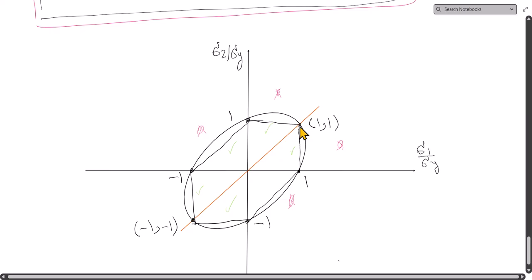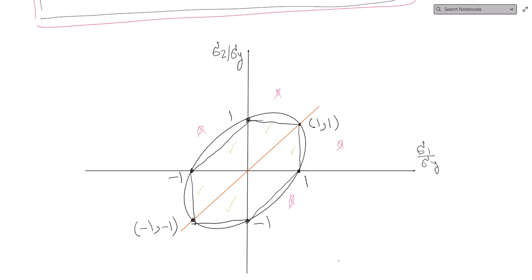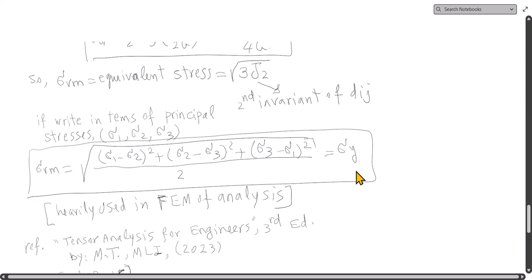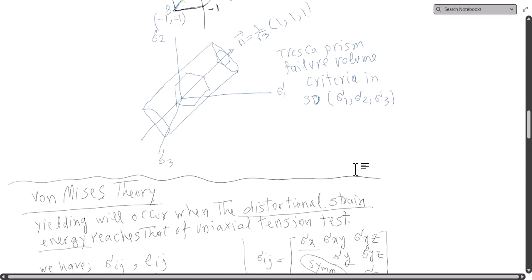And it shows us that if we get a point here or here, between the Tresca and von Mises, let me mark these things. This is the von Mises criteria, and I use this also here, Tresca, that we had before, but you can draw it again here on top of each other.